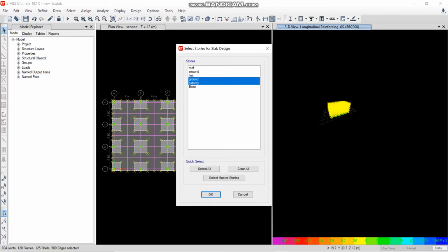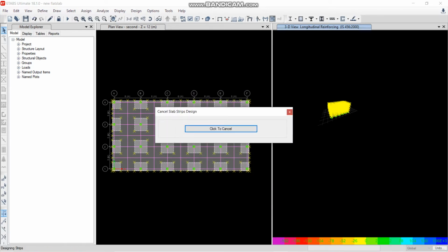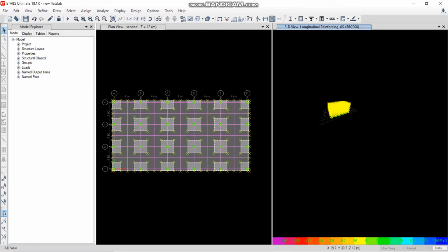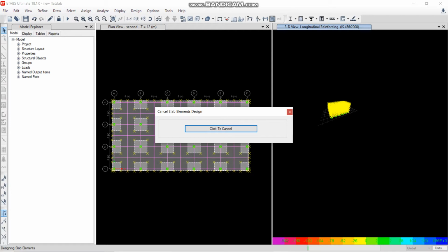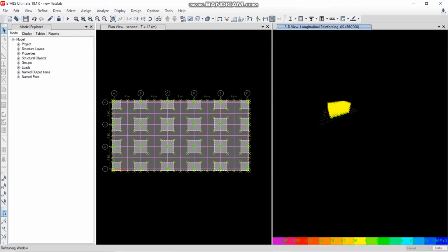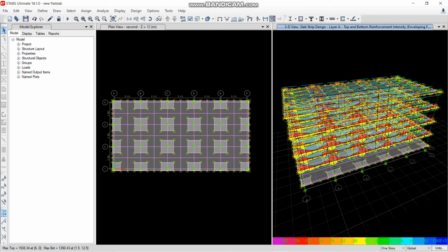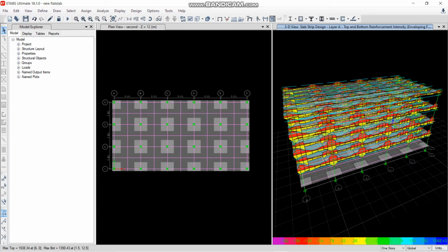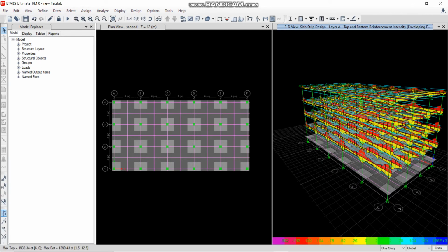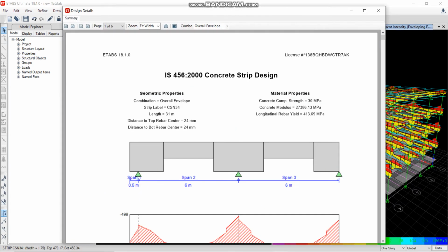Now there is one thing that we have to do. I missed it, because in the plinth story, there are no slabs, there are only beams. So if you input some details based on the template requirement, then the flat slab will display or model the default drop slab structure system. So you have to manually delete the plinth story slab, and we have to assign the beams.